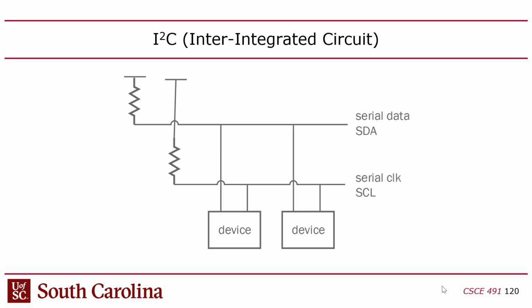Okay, but you might look at this and say, wait a second, hold on, where is the slave select? Like, how do we know who's taking the mastership, right? And also, I noticed that there's only one bit line. SPI has 2 bit lines, MOSI and MISO. It's bidirectional. This is not bidirectional. This is a simplex protocol. SPI is a duplex protocol.